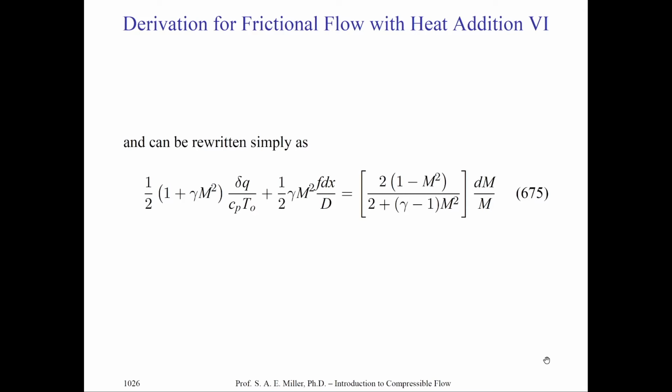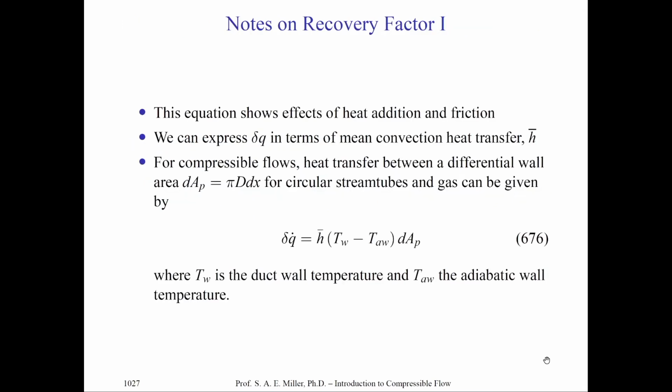Now we have an equation for Mach number given a particular change in heat transfer and an initial stagnation temperature, where Cp is a constant, when F and D are frictional effect and diameter. So we seek to try and solve this type of equation. And note, we've made no assumption about cross-sectional area being constant like we have in previous lectures.